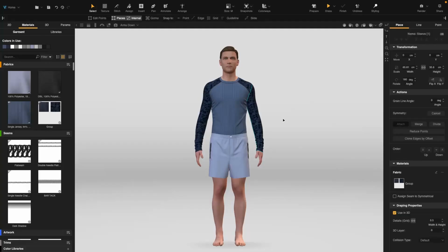When we right-click in the 3D view, some options are displayed. To view the options, we must right-click using the mouse and hold. When we place the cursor on the background, then right-click the mouse and hold, these options are displayed: Show 2D window or Maximize 3D window, Reset view, 3D annotations, Load related avatar, and Edit lights.